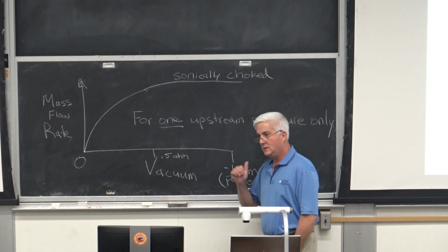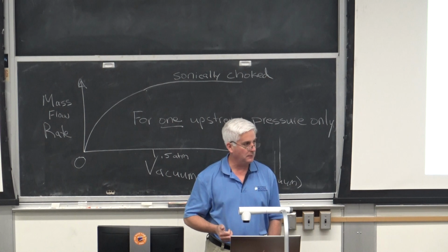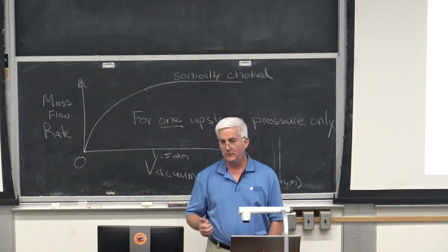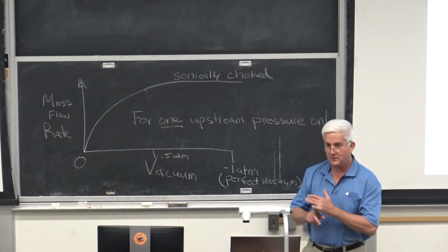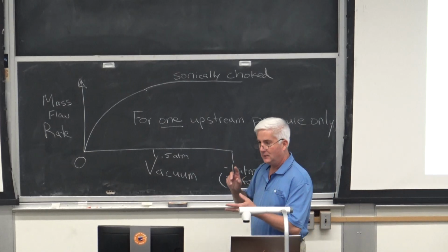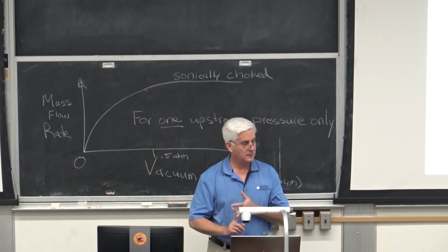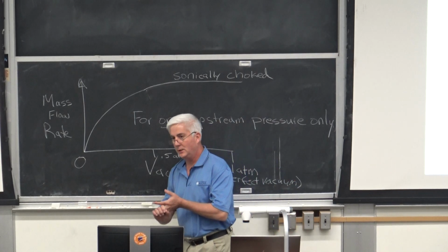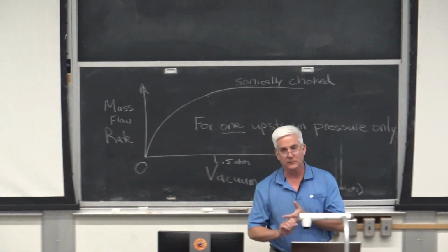Speed of sound is totally and only dependent on temperature, which never felt right to me, but it is absolutely true. So things like kinematic viscosity, density, pressure, none of it matters. As long as you're within the realms of playing with an ideal gas, only temperature matters for the speed of sound.